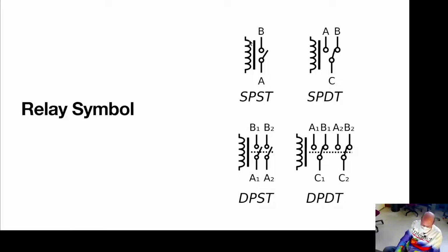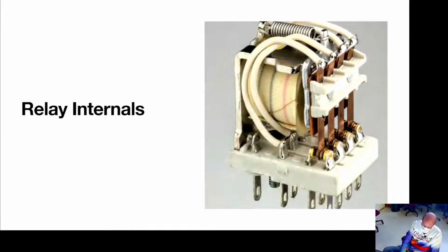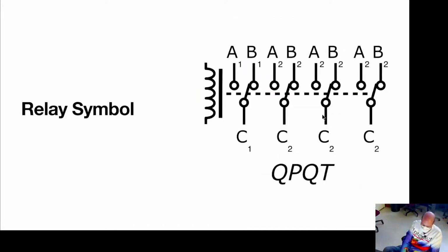So a simple relay would just have a single normally open contact and a relay coil, but you can have a contact that toggles between normally closed, the C and B, and normally open, or multiple such contacts, or this big relay would turn into this kind of monstrosity.